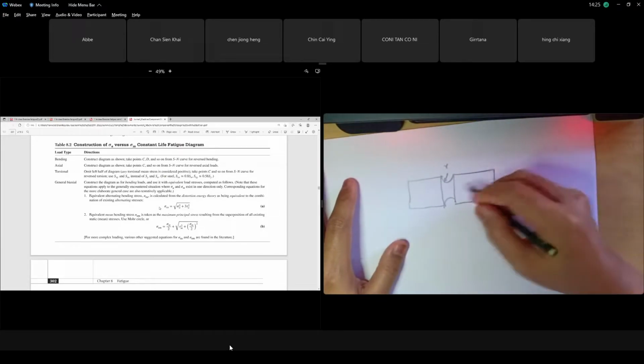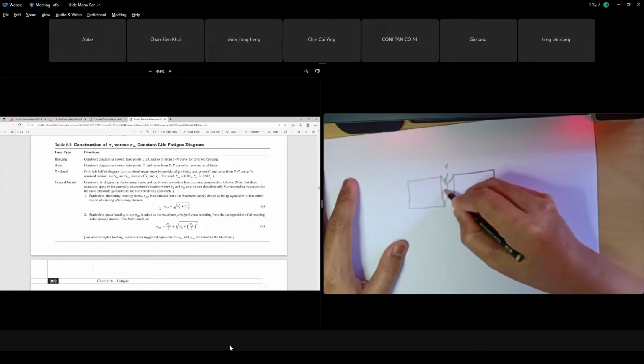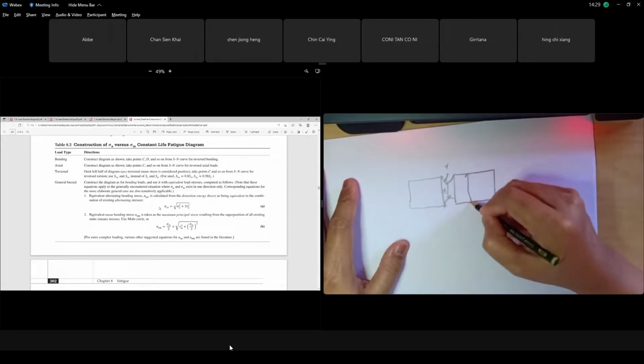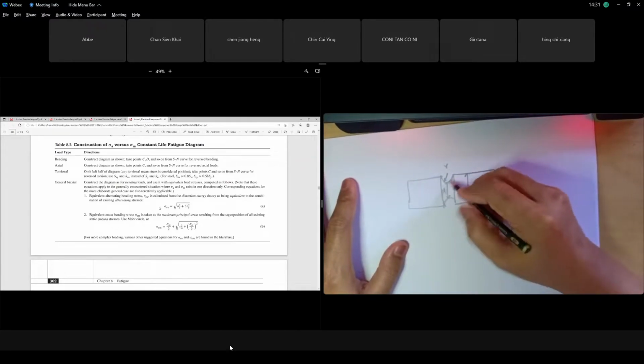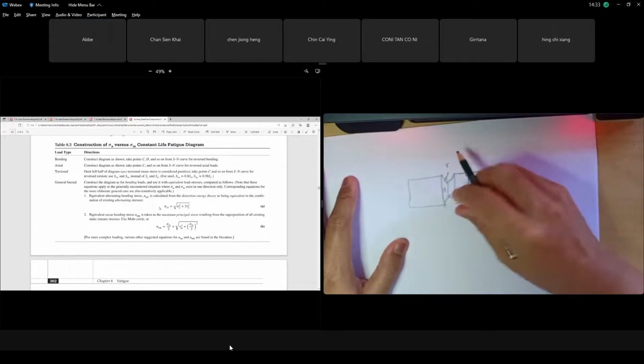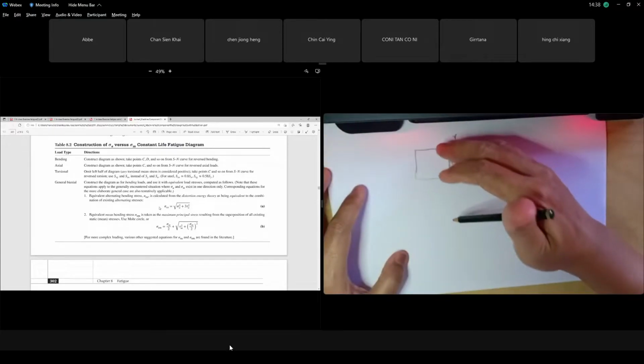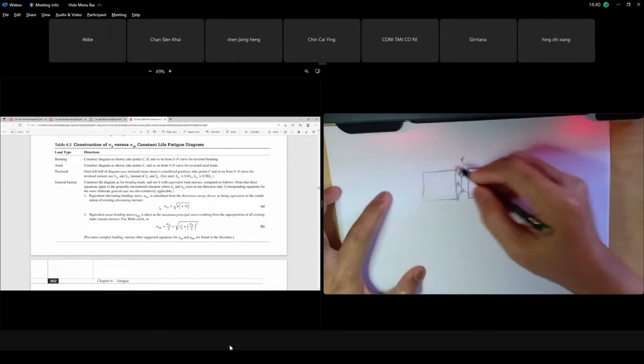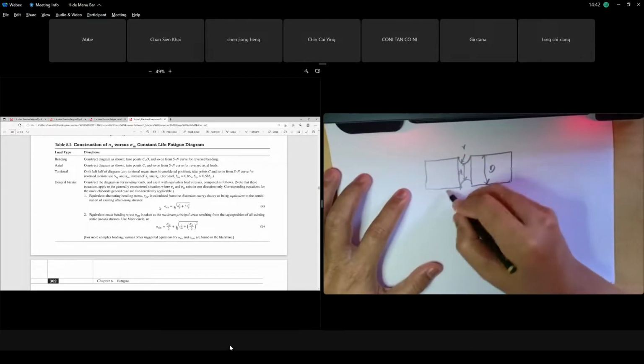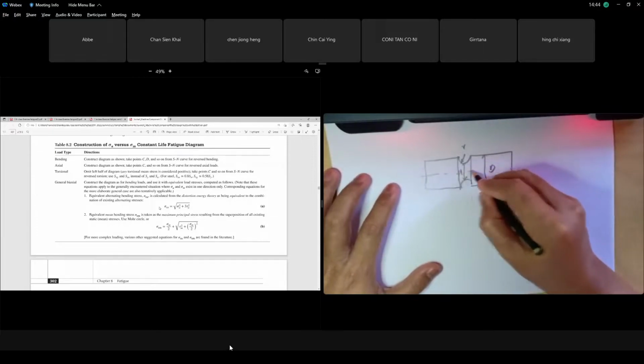You have a small radius there, and you have a small d diameter here, because capital D is your major diameter. Small d is after you deduct 2 times the radius. You have a smaller diameter and a bigger diameter. So they have stress concentration. If this one has bending, has moment, and you bend this thing, and this is your neutral axis.